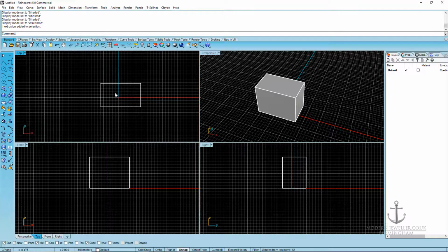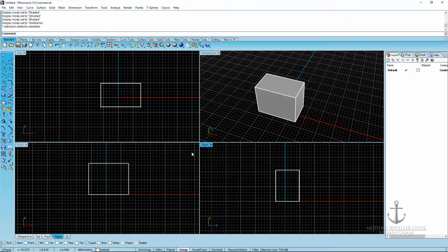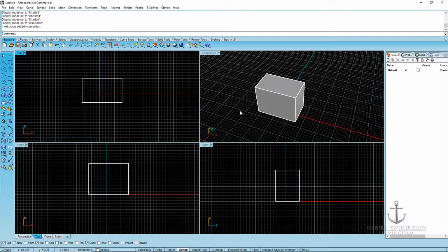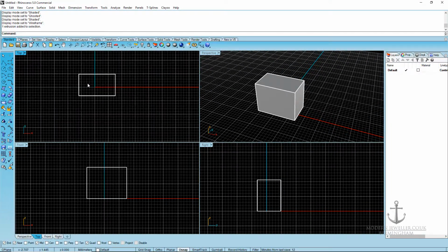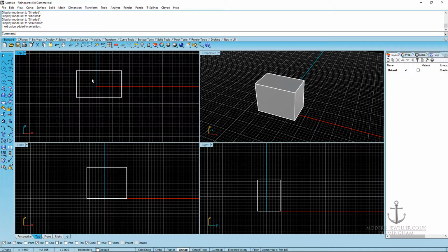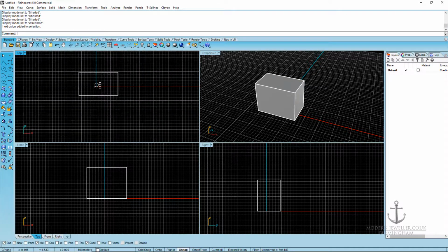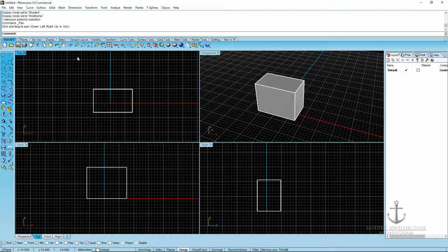These three viewports show objects two-dimensionally. So you cannot rotate inside the scene. Zooming methods in these viewports are the same as the perspective viewport. Also, you can navigate viewports through the standard tab. This is the pan command, and as I mentioned before, this command shifts the location of the view camera and target parallel to the view plane. You see the rotate and zoom buttons.